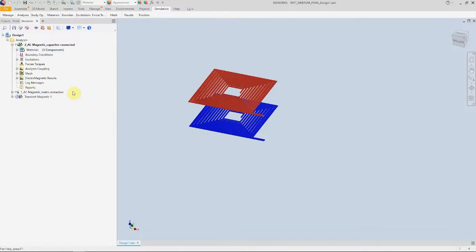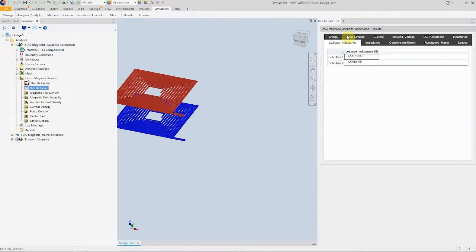At the first step, I used the AC magnetic to calculate the inductances of the coils to be able to calculate the resonant frequency. As we talked, if you want to increase the quality factor and the available power transfer, the circuit should work at the resonant frequency.